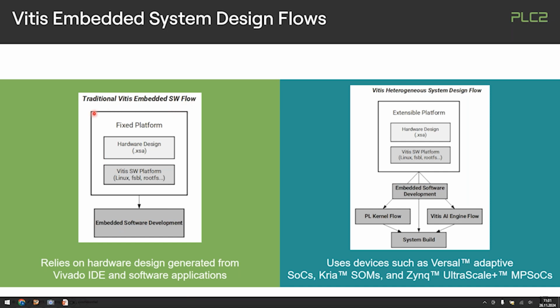You're fixed: you're building your address map and the IPs that you are using, configuring that, and you would hand the address map into the software development, plus the information, of course, on what certain parts of this address map should do. That's a very traditional flow for embedded designers, like microcontrollers that you can buy, which will not be able to be extended. It's quite common for the Zynq UltraScales and even for the Zynq 7000s.